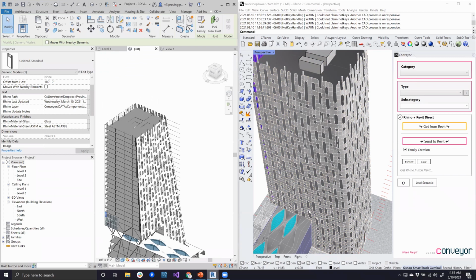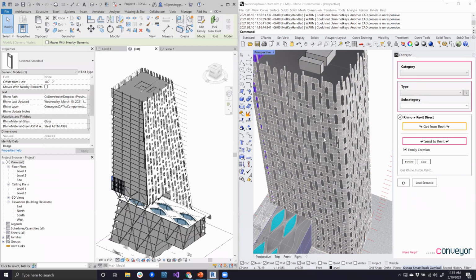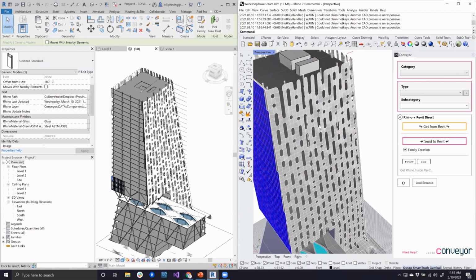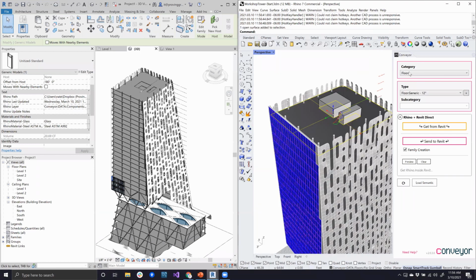If I click on, say, this surface, and I look at the categories, this category list becomes filtered down to things that a user may want to classify the surface as. I'm saying it's a floor, but maybe I do want to bring this in and classify it as a structure. So it'll become a surface element that has a structure classification, face-based wall, things like that.